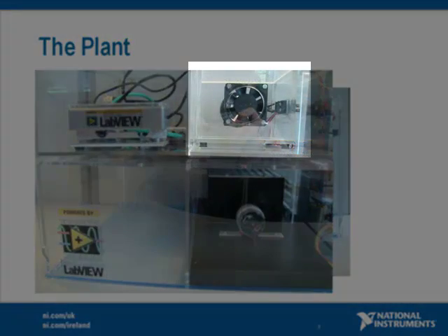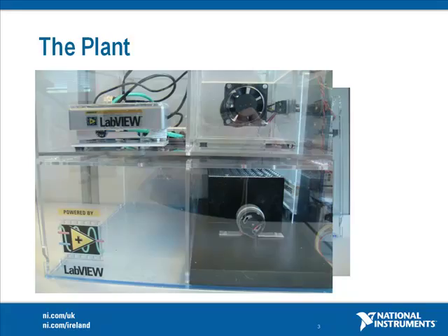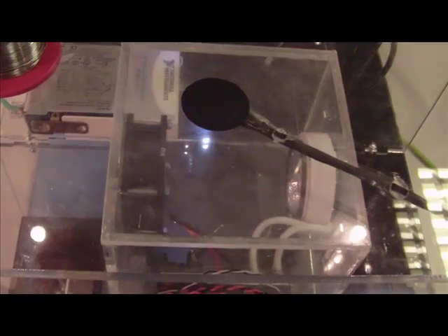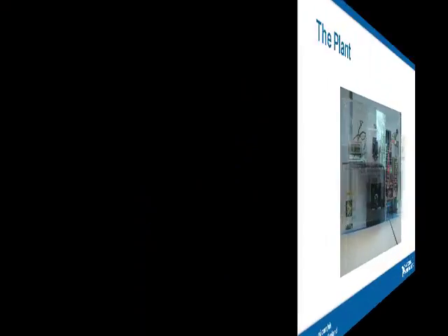We used the scan mode with a digital I/O module to send PWM signals to our temperature controlled furnace. A light bulb would increase the temperature of the furnace and a fan was used to decrease the temperature. Closing the loop on this control was a thermocouple input. The outputs were all set using a tuned PID algorithm.